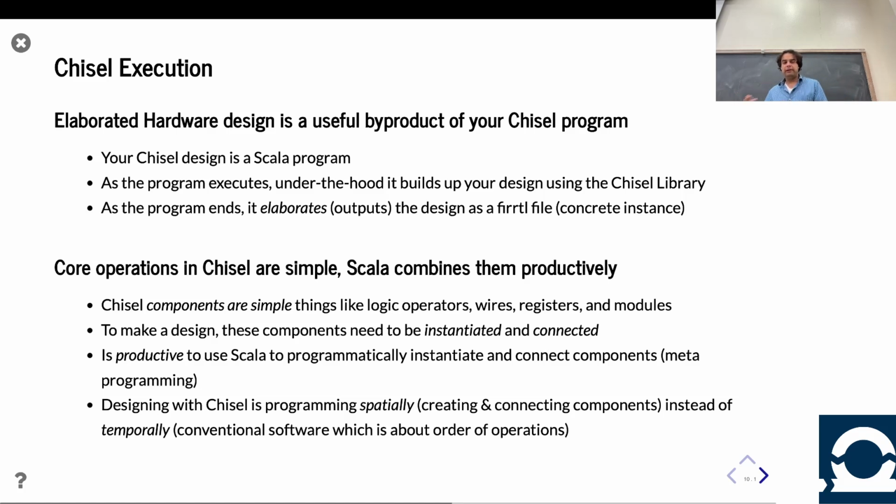And what does it look like? Well, actually, when you're writing Chisel, in a way, you are thinking about things spatially, right? With Chisel or even Verilog, you're thinking about describing the structure of a hardware circuit. Technically, in Scala, with Chisel, you're making a program that generates that circuit, but still, same idea. You're thinking about what is a spatial component I want to build, versus when you normally write software, you're thinking about a sequence of steps. In this case, less about a sequence of steps, more about what is the physical thing I'm trying to build and how do I go about describing that.